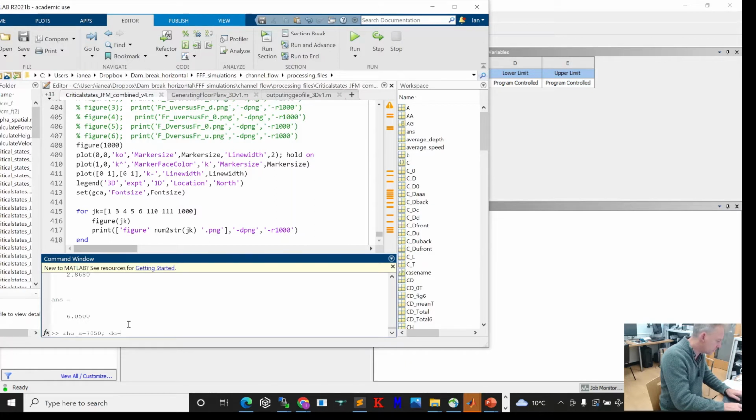We've got D external being 813, D internal being 793.94, and we've got rho LNG equal to 455. So rho effective is basically rho steel plus rho LNG times DI squared divided by DE squared minus DI squared.